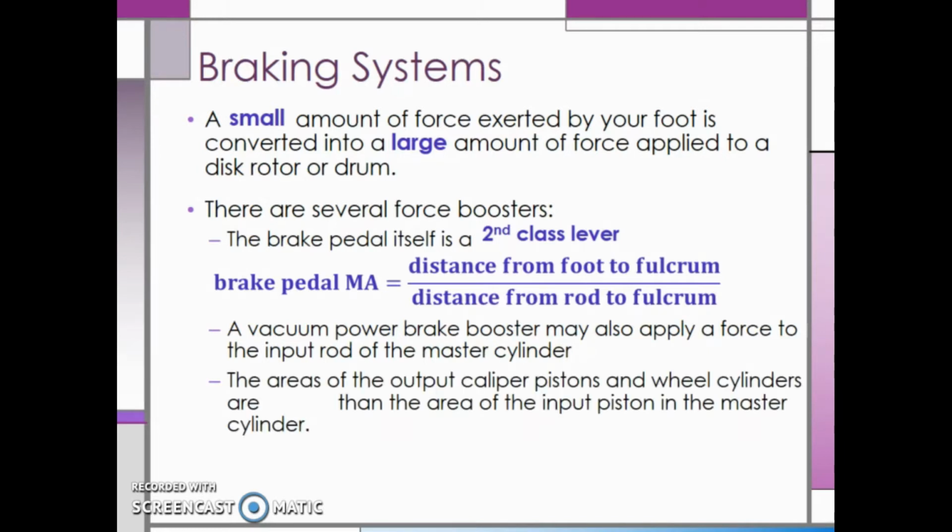Remember, the areas of the output caliper pistons and wheel cylinders are larger than the area of the input piston in the master cylinder, so the output force will be greater. In the next video, we will take a look at some calculations related to brake systems.